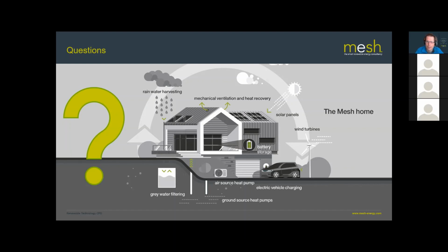Yes, we had. In fact, that was something I talked to the PV expert at Bowder about a few days ago. The general rule of thumb is if you've got a roof which is susceptible to that kind of damage, the best option is to just put the panels slightly further back from the edge than you normally would, because it makes it harder for them to be vandalized. But yes, that is a concern. They are made out of glass. They're pretty tough, but they are breakable ultimately.